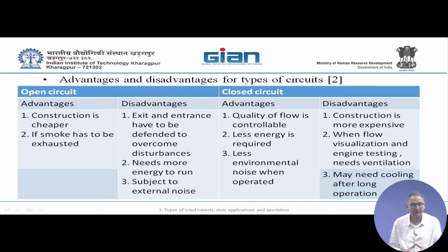This is a net energy that you have to invest continuously. In addition to this, you also have to invest in the drag friction that you have in your open loop. So you have two contributions to the power that you need. One is the acceleration of air. Second is the energy loss due to friction or whatever you have there.